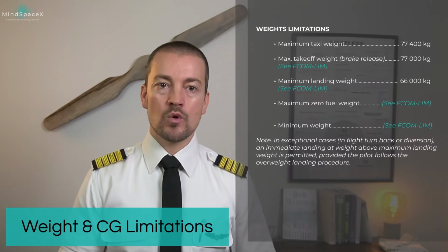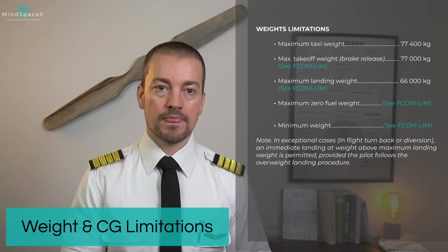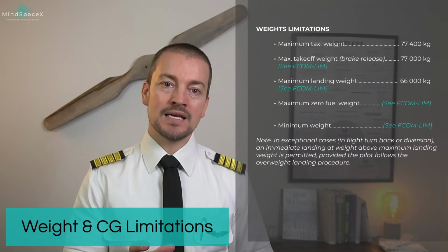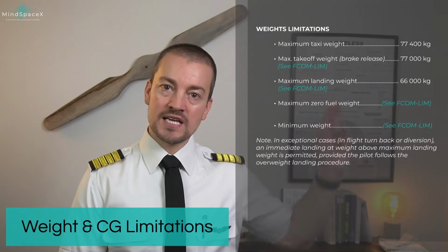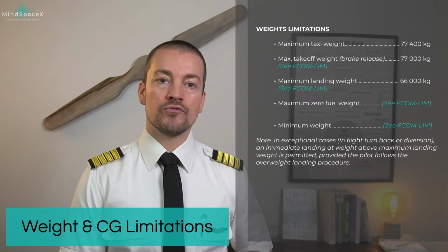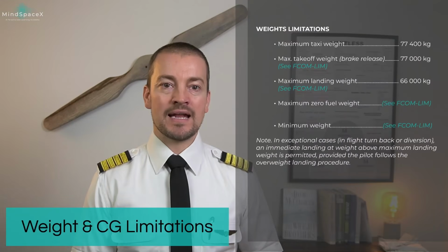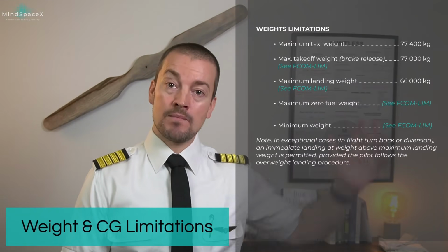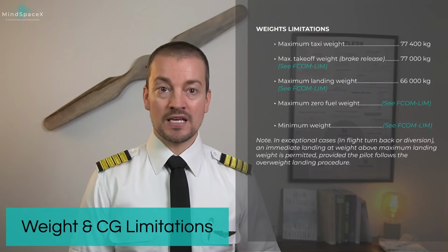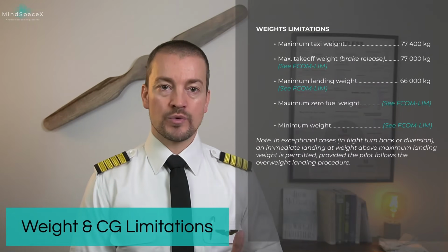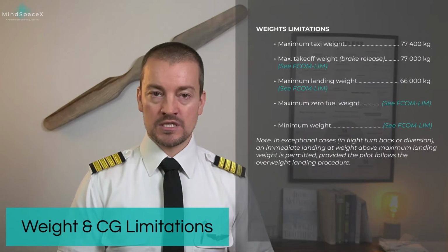This aircraft is not equipped with fuel jettison equipment, fuel dumping capability. Aircraft that can meet the landing requirement structurally at full takeoff weight do not require fuel jettison equipment. So if we have to come back and land immediately after takeoff at our maximum takeoff weight, we can do so knowing the aircraft is structurally strong enough to withstand that landing, provided we follow the overweight landing procedure.